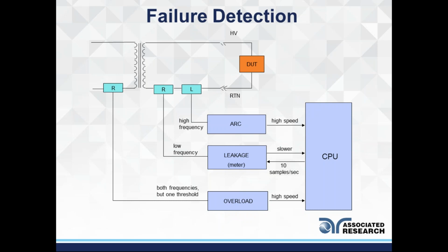And in many cases, arcing conditions can be seen as a luminous discharge caused by the ionization of air molecules, and that's why it can actually be seen in a dark room. If there's arcing going on during a Hipot test, you can actually see that discharge, and in other words, that's called the corona effect. What's going on is that high impedance arcing is a temporary condition. It's not necessarily considered a sign of breakdown, because again, we know what a breakdown is. So arcing is not considered a sign of breakdown.